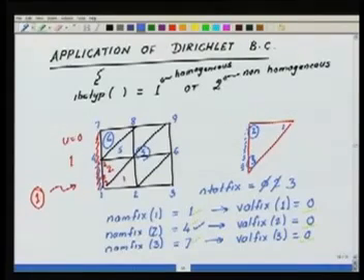If I look at the fifth equation, that is the equation corresponding to the global 5 degree of freedom, this equation will have contribution from elements 1, 2, 4, 5, 7 and 8. Okay. So really it has contributions from 6 elements, because there are 6 elements which are sharing this node amongst themselves. Similarly, if I am talking of the third node, this will have only contribution from the third element. No other elements actually participate in this node. So you see that I can have contribution to a node coming from 1 element, from 2 elements, from 5 elements, from a varying number of elements.